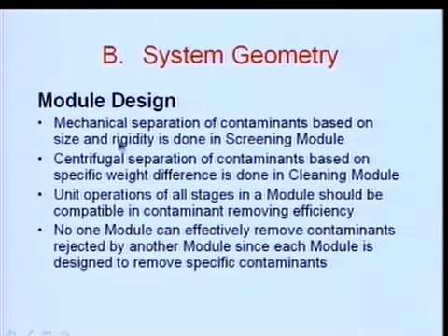So, module design comes back to the design of the whole system again, and basically in here we are saying, mechanical, again back to the modules, mechanical separation of contaminants based on size and rigidity is done in screening modules. And then going further, centrifugal separation of contaminants is done in the cleaning, and this is based on specific weight difference. Unit operation of all stages in modules should be compatible in contaminant removing efficiency. We just saw that between pulpers, screens and cleaners.